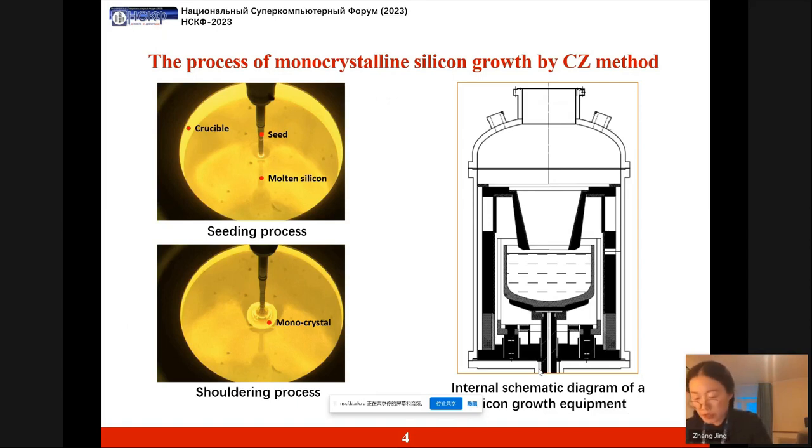The crystal equipment involves heating high purity semiconductor-grade polycrystalline silicon to a molten state within a container, like this. A crystal seed is placed on the end of a predetermined-orientation polycrystalline rod, which is then immersed into the molten silicon. Subsequently, the rod is slowly pulled upward while simultaneously rotating.